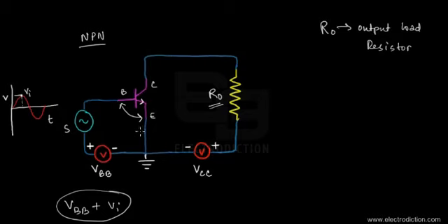That triggers the recombination process within the base region, which further attracts electrons from the emitter region into the base region, and that causes a current to start flowing through the BJT. The current that flows through the BJT would be coming from the voltage source VCC at the output terminal.